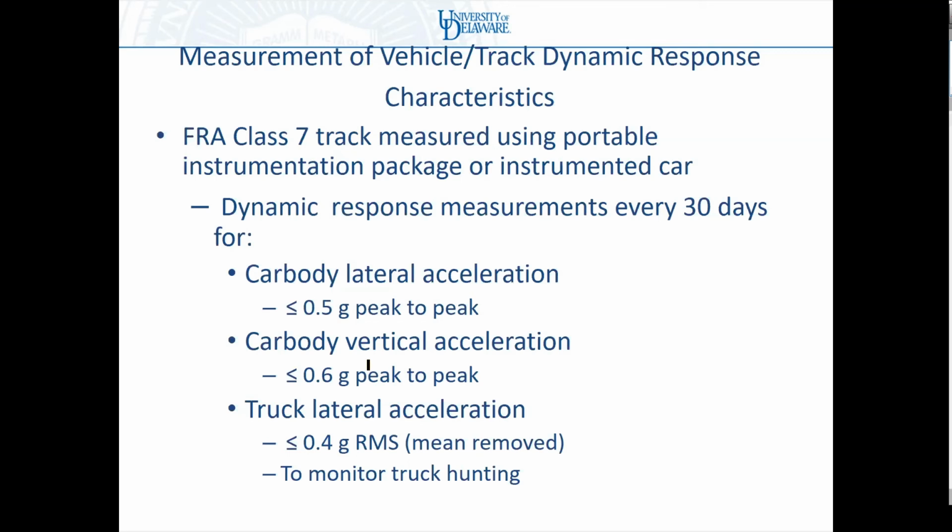In fact, there's a new class of measuring equipment called vertical track interaction equipment. For example, in the United States, we put these VTI, or vertical track interaction, packages on locomotives, and they measure the dynamic vertical, lateral, and longitudinal accelerations.